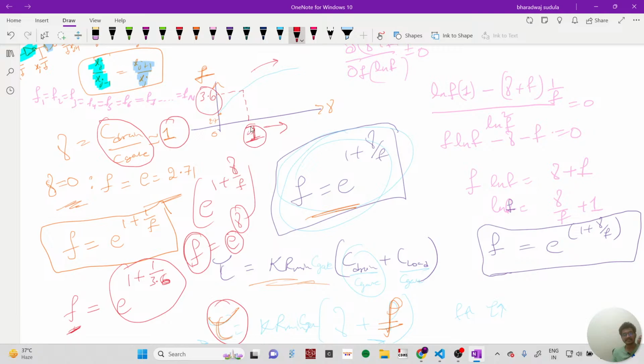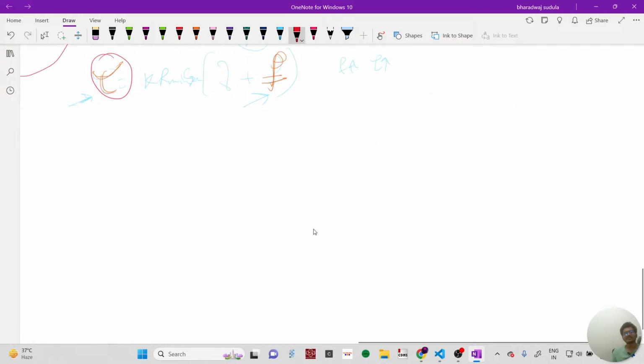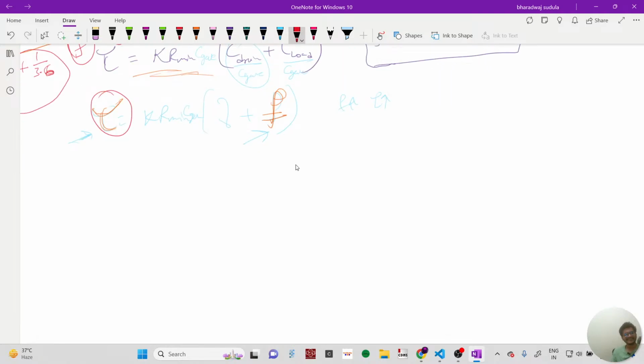So ideally, for an optimal value, we consider gamma as 1. Minimal value, optimal value, gamma as 1. But that comes out to be 3.6. So in order to reduce some hectic calculations, like it will be cumbersome, we approximate this 3.6 to 4. Okay, this is FanOut 4. Why FanOut 4?